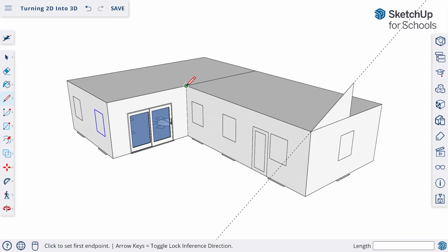Now that we have the profile in place, we need the path to also be around the perimeter of the model. But this edge here that breaks the two main areas will prevent us from having it follow the entire perimeter of the model. So click on the eraser and then click to erase the edge of that top surface. If I undo, you can also take the select tool and just single click on that edge as well and then press delete. Both will remove that edge.